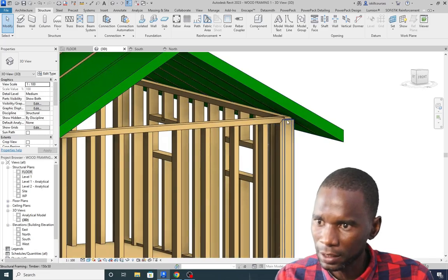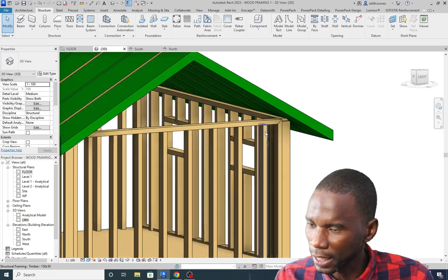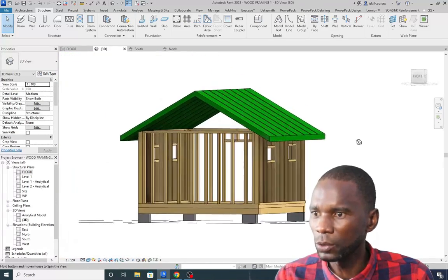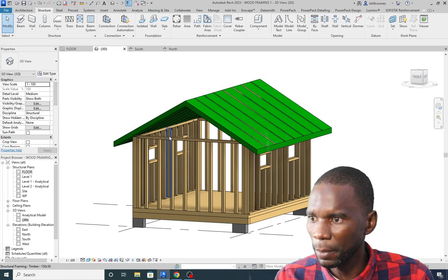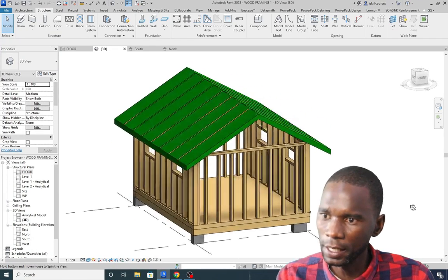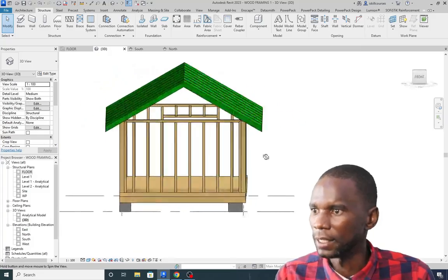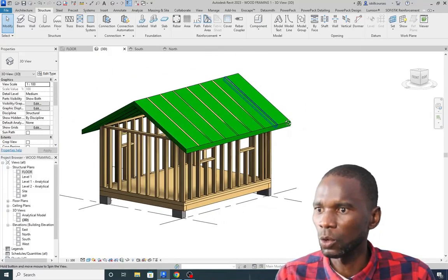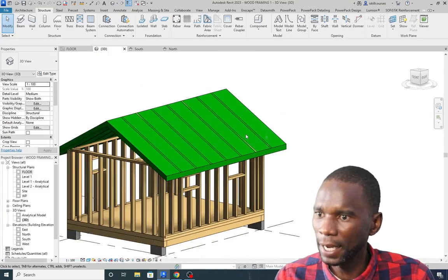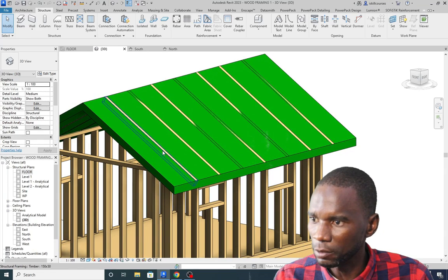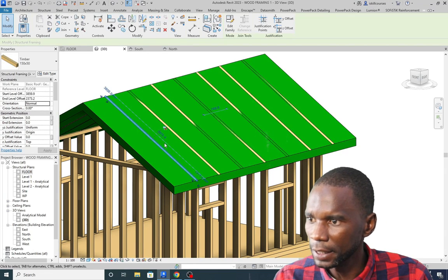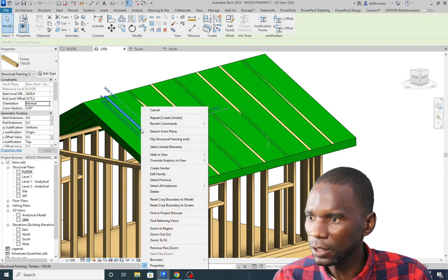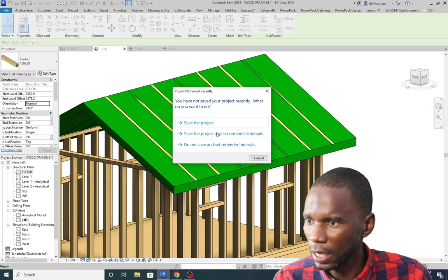It's simple, just you copy this member and place another one on top. You have all the tools that you need to use to place some more members on top so that you have a double there in terms of the beam there, the wooden beam. Okay, so what I would do, I have those members there, and what I'm going to do is to simply first of all pick that member and pin it. Okay, then I want to right click and create similar.